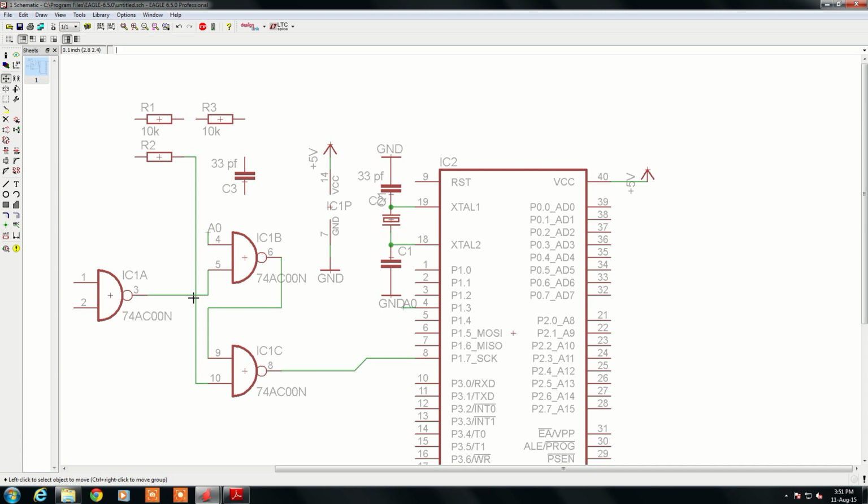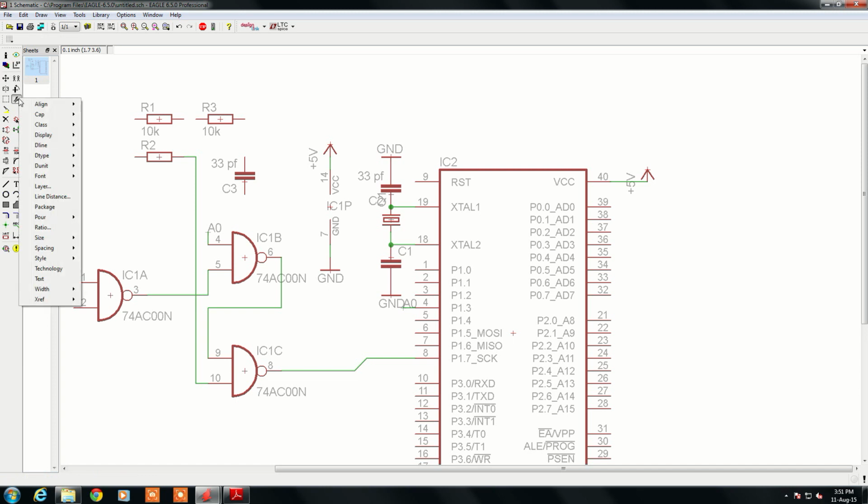So these are some of the commands. If at any point of time you want to change any of the components, then you can use this change command. With change you can modify the width, font, display types, the values and so on, directly.